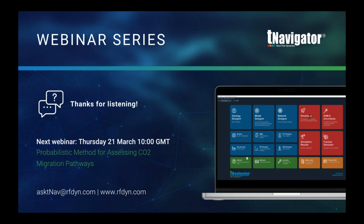Do we have any petrophysics tools to help edit our logs and calculate V-shale, porosity, saturation, permeability? Obviously, Jordan, you probably covered that with some of your videos, but we're constantly adding more petrophysical functionality with each new update. At the moment, for your logs, when you go to your calculations, we've got a dedicated petrophysics tab. When you click on that, you can find your water saturation, Simandoux equations. You can find your porosity, density, and permeability equations within there.